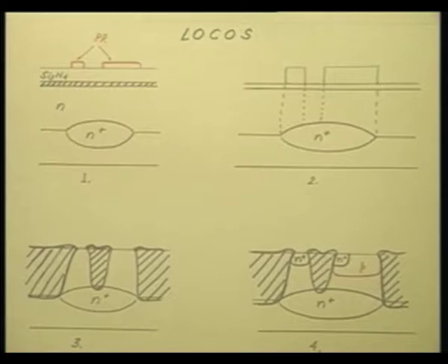Si3N4. This has to be chemical vapor deposited silicon nitride, stoichiometric silicon nitride. The plasma deposited ones do not work very well. So, most people use chemical vapor deposited silicon nitride. So, on top of this you have chemical vapor deposited silicon nitride, and then you have a photoresist pattern on that. That is, some regions of the silicon nitride are protected by photoresist. So, this is your first figure.